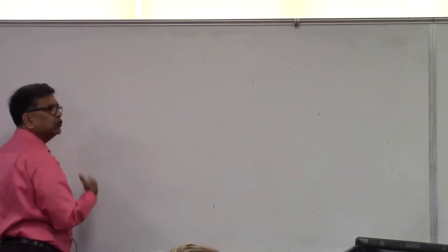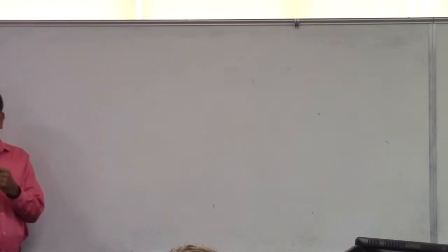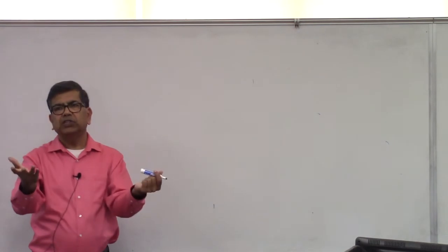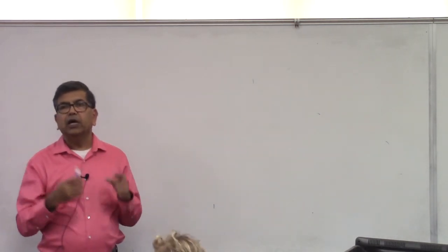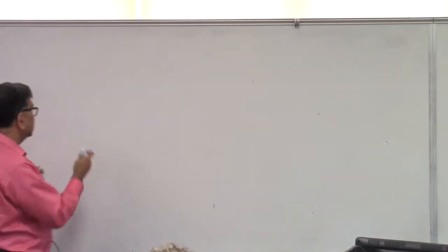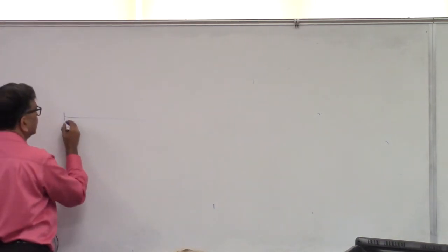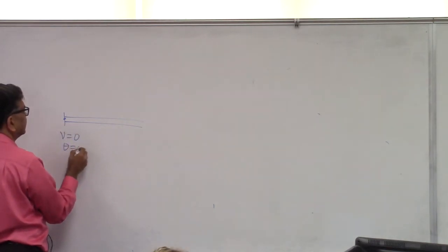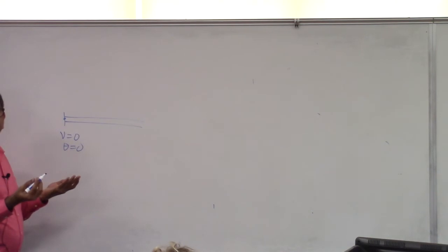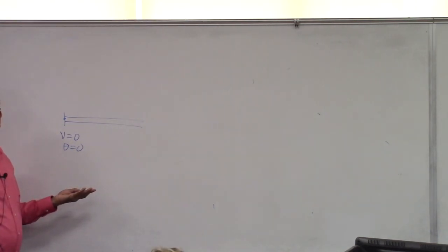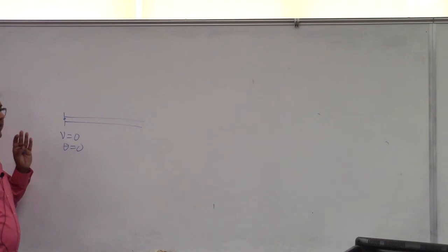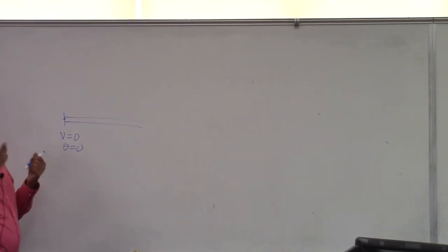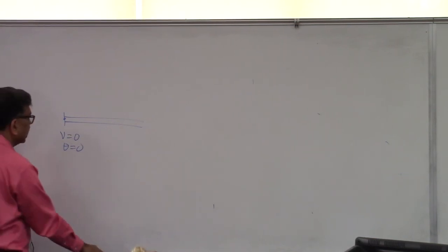So now what we have done is we have chosen the function. If you have done a Rayleigh-Ritz method already, you know, I give you the function, but here the function is already given. I told you it has to satisfy the boundary condition. The boundary condition is already satisfied, because if you use a cantilever beam, we know at this point V equal to 0, theta equal to 0. The polynomial, we input that. So the boundary condition is also automatically satisfied in finite element method. So we have a very admissible deflection shape. Now we have to choose the correct one using the minimum potential energy principle.